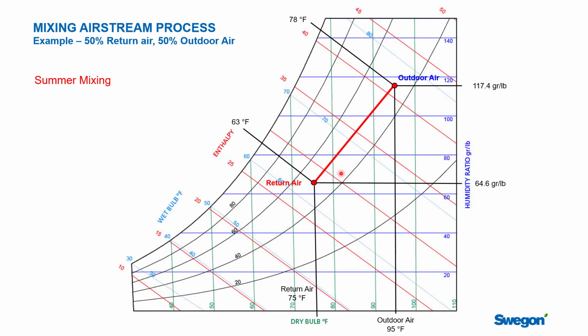This is the return air in the building. And unless you know otherwise, a good place to start is to say that the return air should be pretty close to the design supply air condition of the space. And so you'll often see it described as 75 degrees, and we usually say 50% RH. So you see these sweeping curves here. These are what relative humidity lines look like on a psych chart. So that's 20%, 40, 60. And you can see that dot is kind of halfway in between.